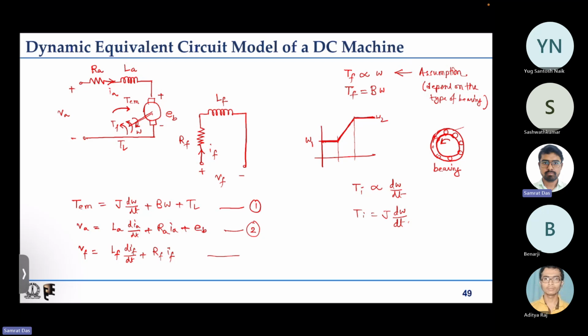And we'll also have something that relates the field winding and the armature winding. The back EMF is dependent on the field winding current, and similarly, for the current flowing through the armature, the electromagnetic torque generation is also dependent on the field winding current, or indirectly the flux. We have understood what we mean by flux per pole from our previous discussion.